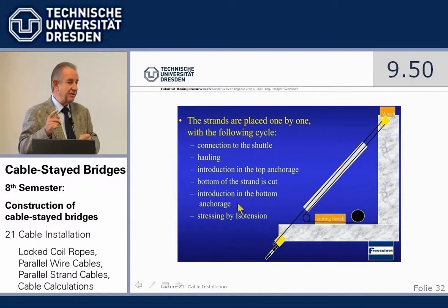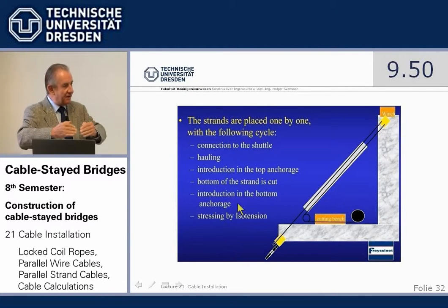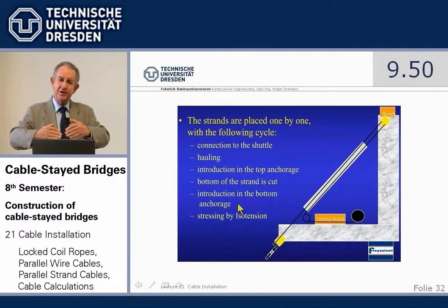And the only critical point is the initial stress of the first strand, naturally. Because from that you go down, down, down, but that can be determined. And so it's a fairly fail-proof system. You just make sure that all the strands have the same stress.